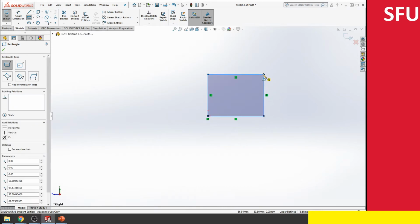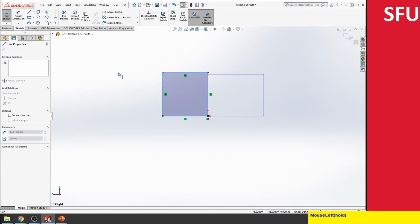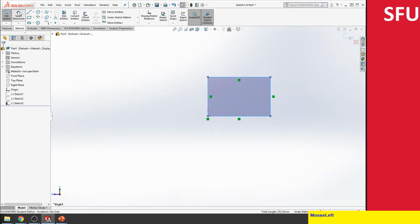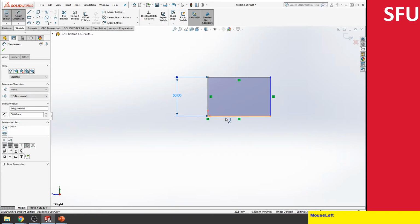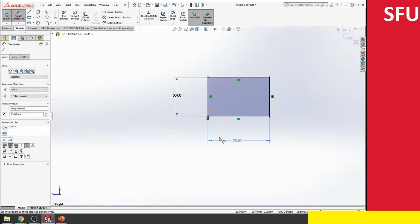That basically makes that particular shape. Once we have this shape, I can set all of the constraints that I want. So let's move this shape around. Notice that the way I created it, one of the constraints is already set automatically to the origin over here. Then I can add some smart dimensions. We call this 50, and then maybe call this 75, and then we say okay here.